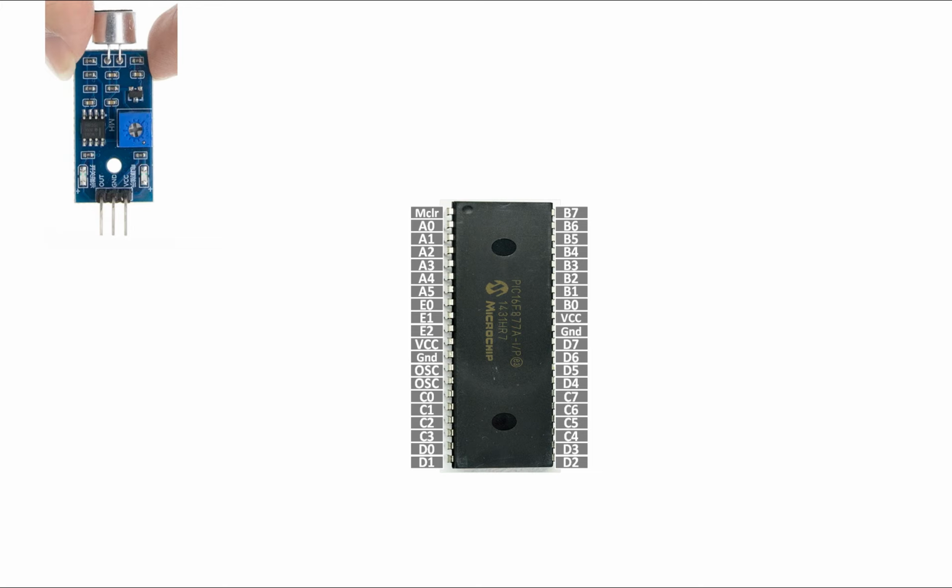So let's first of all do the connection. Let me show you how to connect it. As you can see, it has 3 pins, and as you can see on its body as well, these 3 pins are labeled as from the right. It's VCC, then ground, and then the output. And output is a digital output. Either it gives 1 or 0.